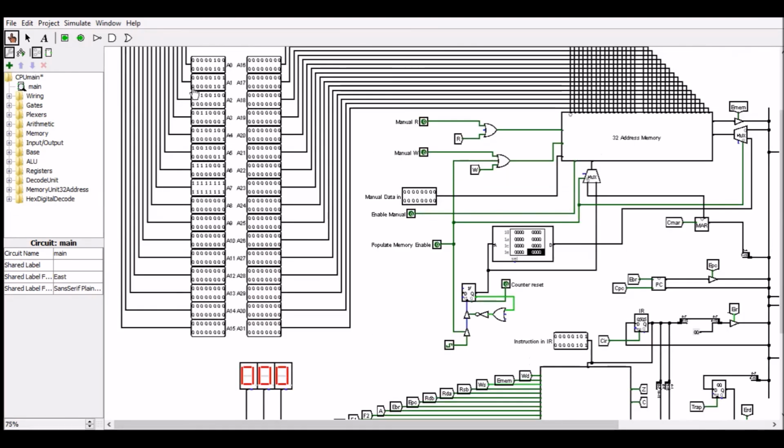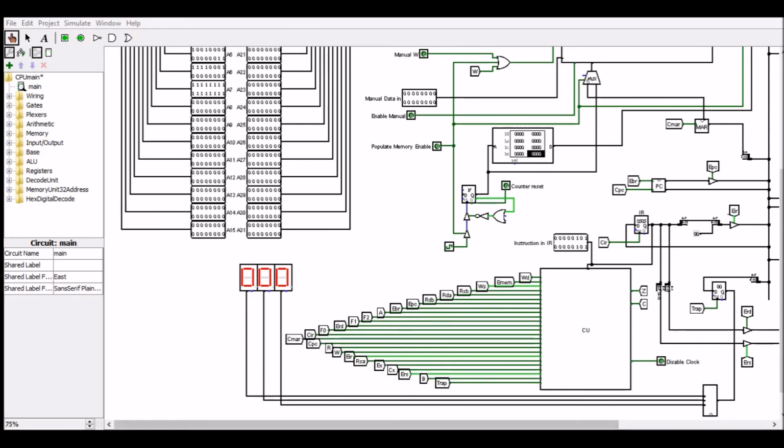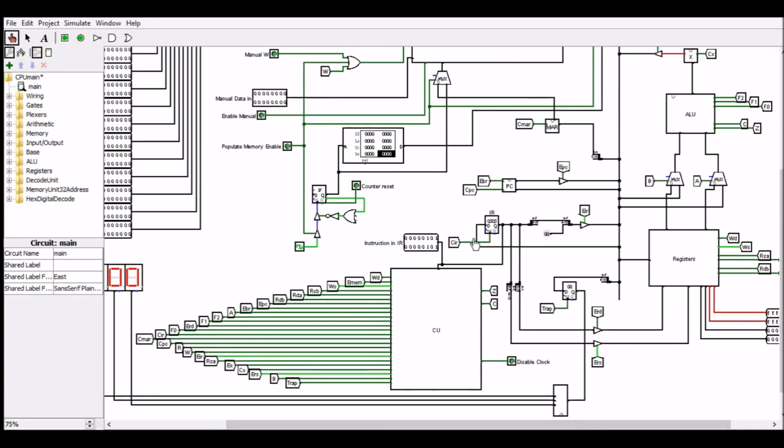And so the operation involves subtracting the literal 1 from the register address 0. So again, it's the same process. Tick to clock the value into the instruction register, then into the execute phase. The instruction register should be enabled that allows the literal 1 into the ALU using this multiplexer.